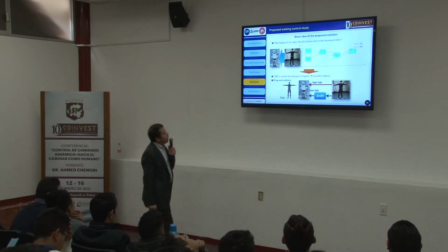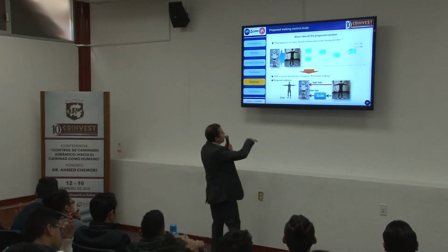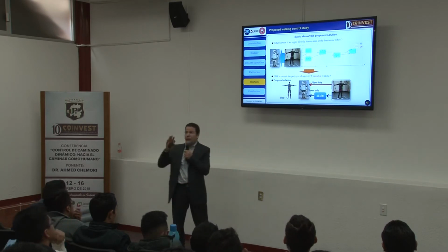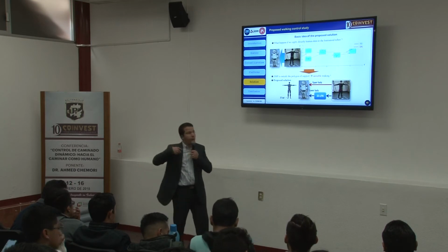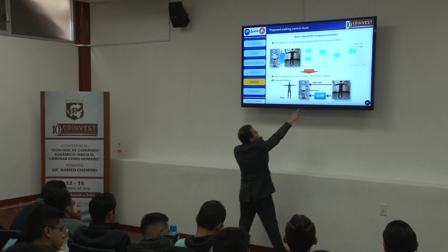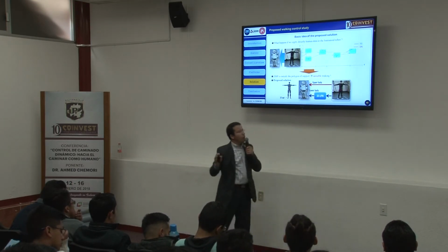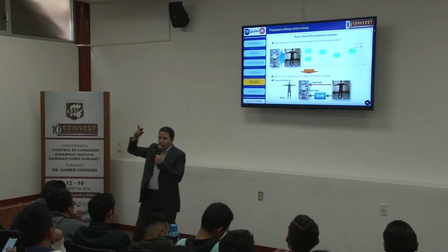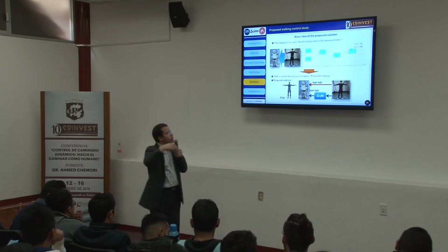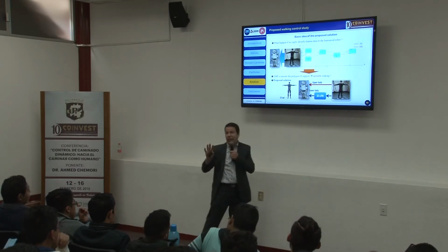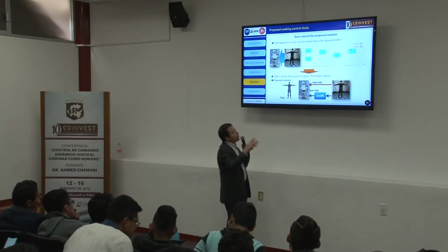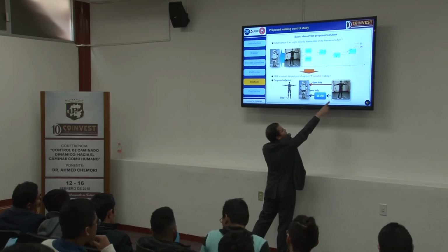And we have proposed, in this case, another solution where we will distinguish the trajectories of the lower body from the upper body. For the lower body, we have used a very simple model, the inverted pendulum model. It's a model very well known in the literature, 3D, introduced by Kajita. And we used this model to reproduce the trajectories for the lower body.